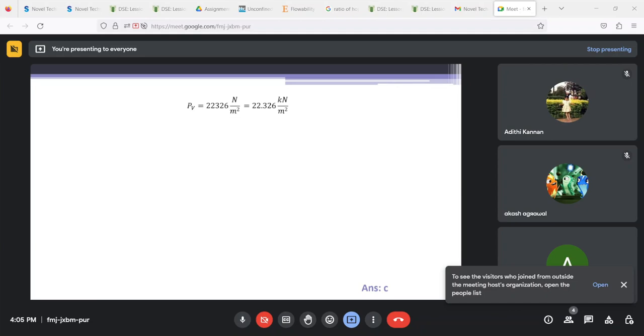So this is the amount of pressure that your silo has to deal with. Accordingly, you will change the material that is required for making the silos. If you know what kind of requirements you have, you can calculate what are the pressures that will be exerted on the silos. Accordingly, you can design your silo in such a way that it is able to withstand that pressure, withstand any changes in moisture content, withstand changes in temperature because of changing seasons. So all those you can calculate by calculating the pressure exerted by the contents inside the silos.